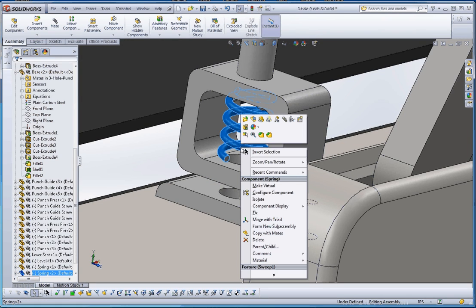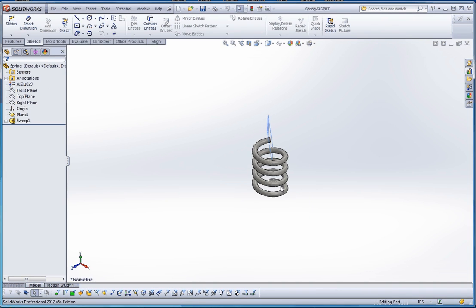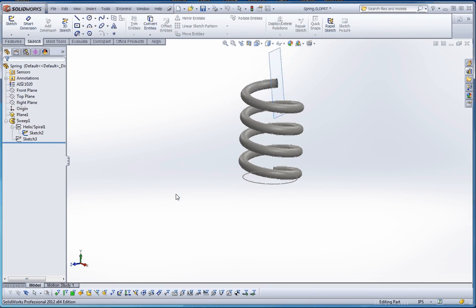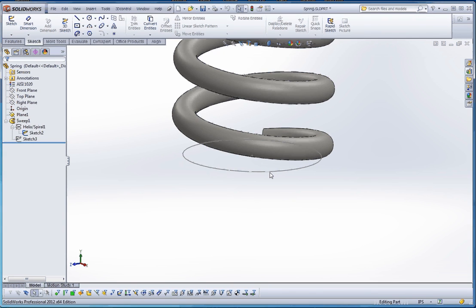So perhaps the better thing to do right now is not to move that around, but let's look at your spring. You probably want to do this with the spring that I showed you how to do. What we want to do is go to our helix down here, go to the base of the helix, and show that sketch. That gives us a sketch element that we use to actually fix that to the base of the punch, if that's how you named it.